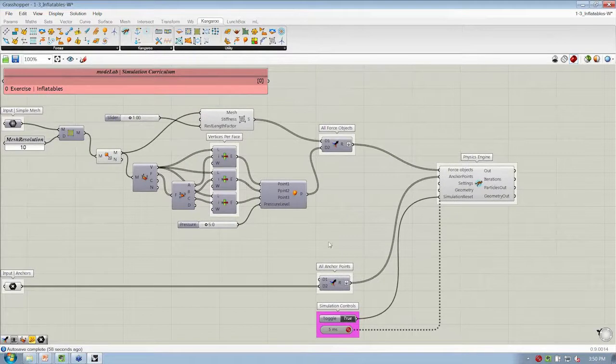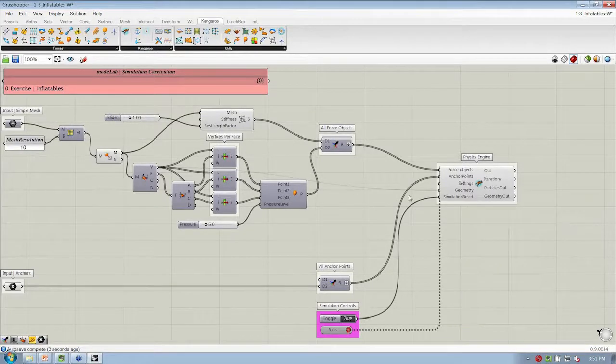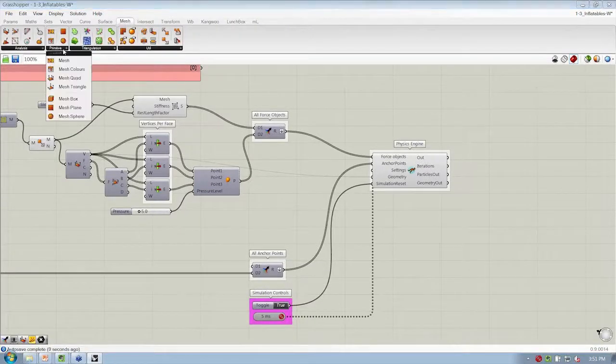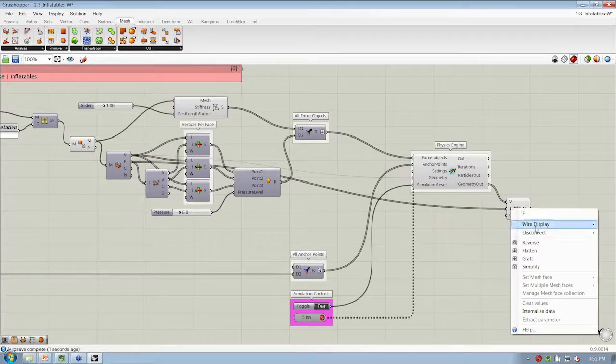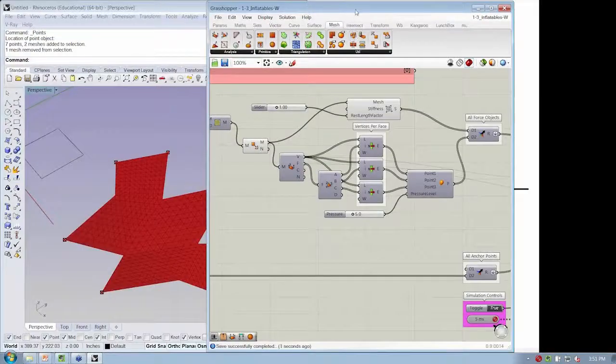All right, so we need to take the vertices of our mesh into geometry. We'll give this a wire display of faint to keep it clean. And then we're going to reconstruct the mesh afterwards. Geometry out. Face commands come all the way from back here. Again, we're going to turn the wire display to faint. All right, so that's face command to face command. Save this.